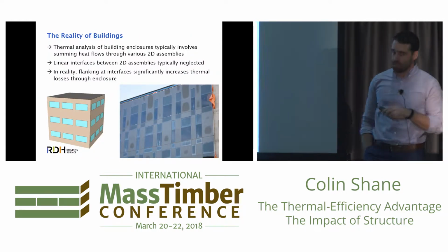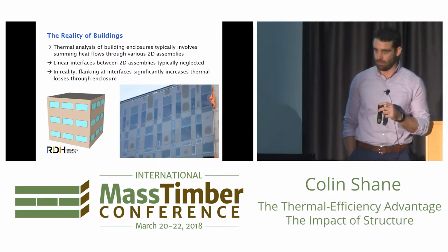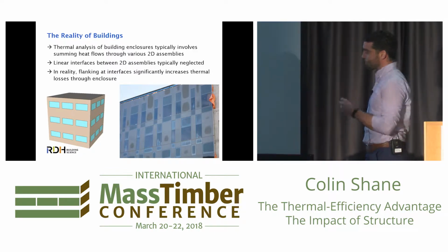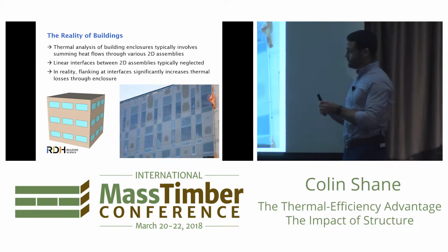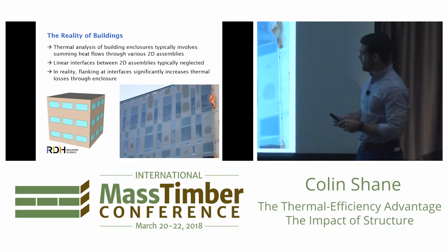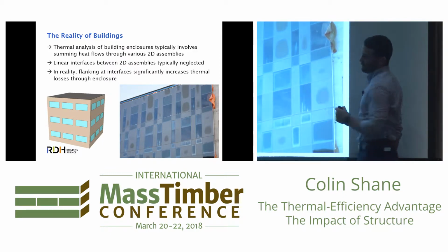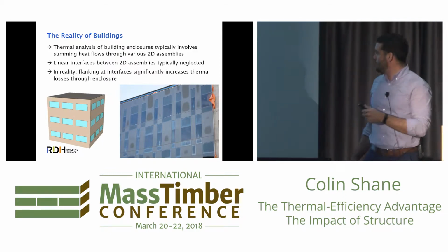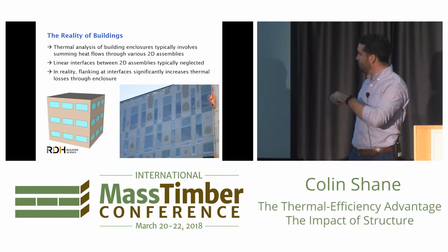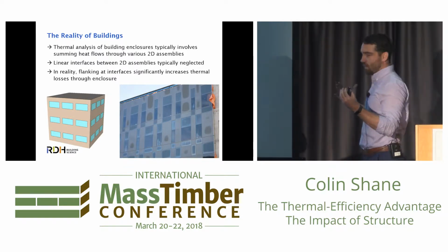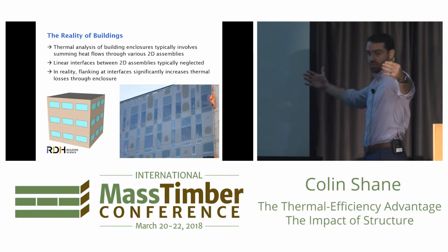What does this picture mean to anybody? Any thoughts? Curtain wall on a steel or concrete building, doesn't matter. But we can see dew on the outside of the curtain wall spandrel panel right there in the middle of the panel, right? Around the outside of the panel, no dew. So what we're seeing here is thermal bridging through the perimeter of the spandrel panel.